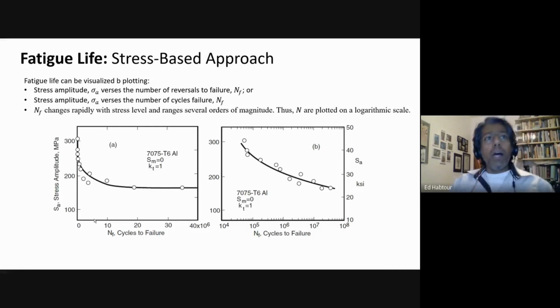All right, so what we're really after is knowing the stresses versus the number of cycles. And that number of cycles is what we call fatigue. For that, we need to know the stress amplitude. Let's say we calculate the stress amplitude and we trace the number of cycles. We know that for each stress, there is a number of cycles associated to failure.